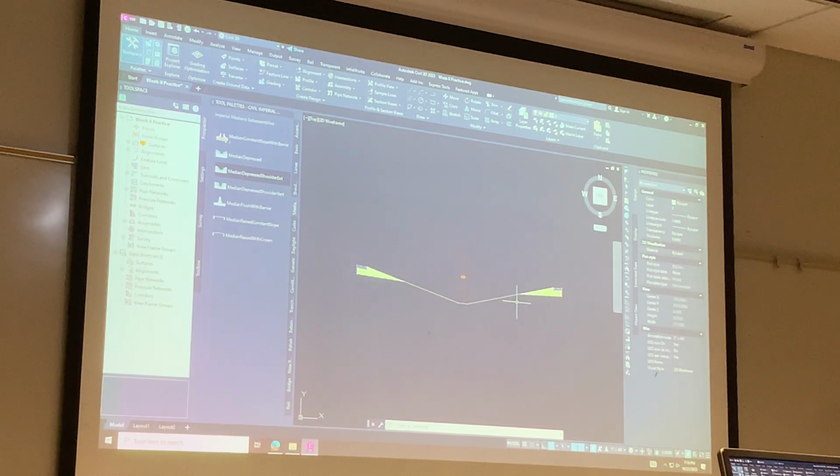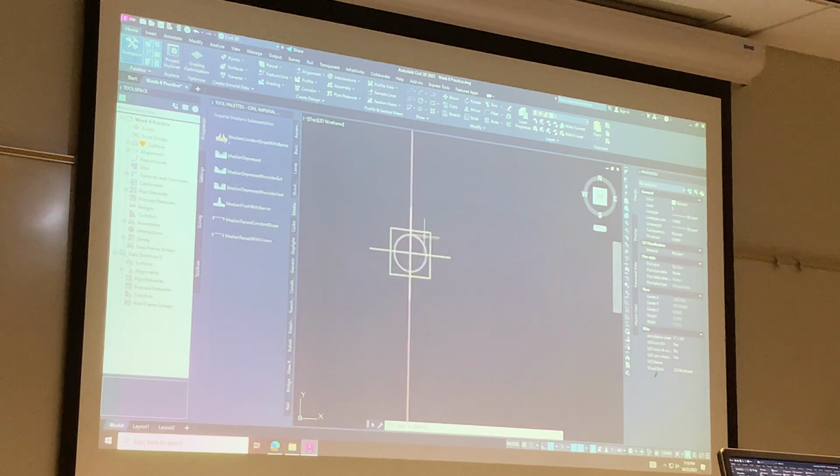Professor, what did you click to after the tool palette? What did you click to get that yellow stuff? Over here? Yeah. On the medians tab, I chose median, depressed, shoulder, extended. Okay. And then I click in the middle. Yeah, and then once you've selected that option, you select the circle in the middle of the baseline of the new assembly. Got it.